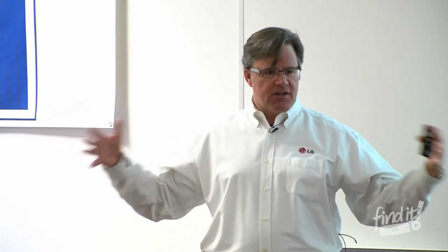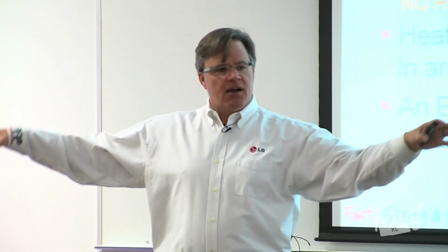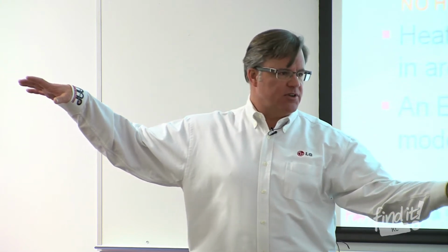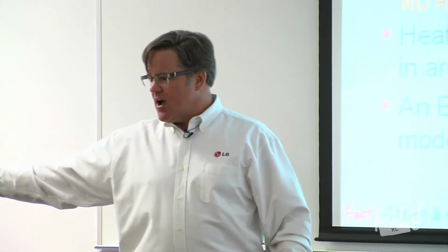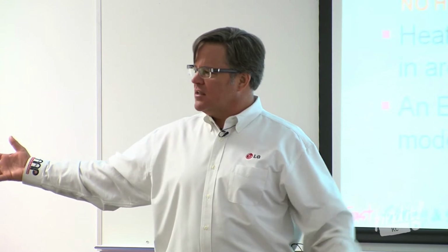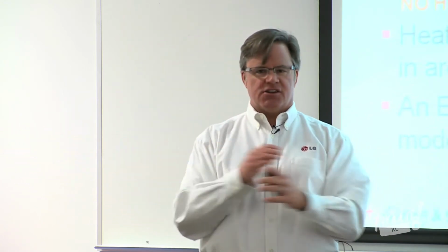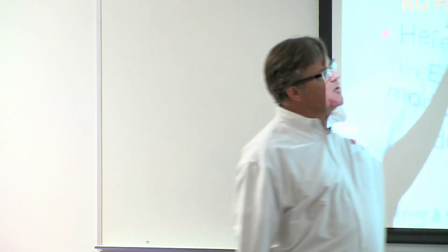Some folks' boxes need condensate, some don't, some are bigger than others. And so designing around one system when you're talking about heat recovery starts to have an impact on building owners and building end users. So the neat thing about this is if you have a heat recovery system, and I've got one guy on one side of my building that needs air conditioning, the other guy on the shady side of the building needs heating, that means those guys basically are exchanging energy back and forth across the building.